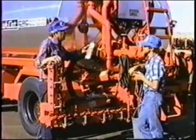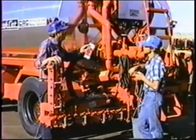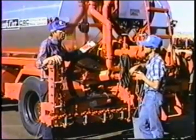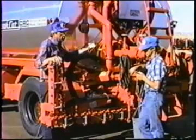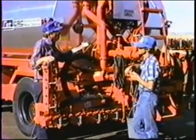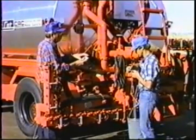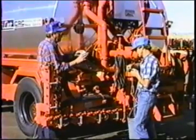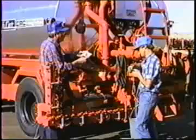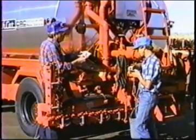From that point, as a spreader truck operator, you've got to make a decision. You've got to decide what speed range, what speed you're going to set up at, and what speed you're going to operate at. And from our vast experience, we've decided on this particular job that we should run 400 feet a minute. So let's take those particular numbers. He told you he wants 0.25 gallon per square yard, and you decided that you're going to run 400 feet per minute. So line 0.25 up with 400.